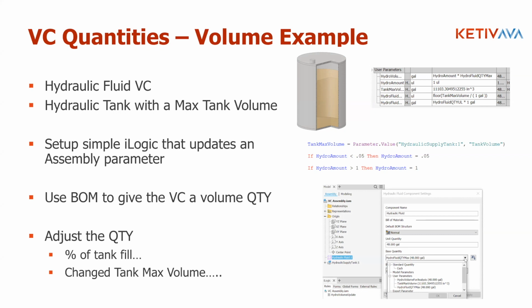They can only be children of the file they currently live in. So when you copy and paste between assemblies, that technically creates a complete second copy, because it's like you copy the definition from one file and you recreate the definition in another file. That is actually what's going on under the hood. Yeah, if you want them to be children of multiple files, an empty part is the best way to do it.